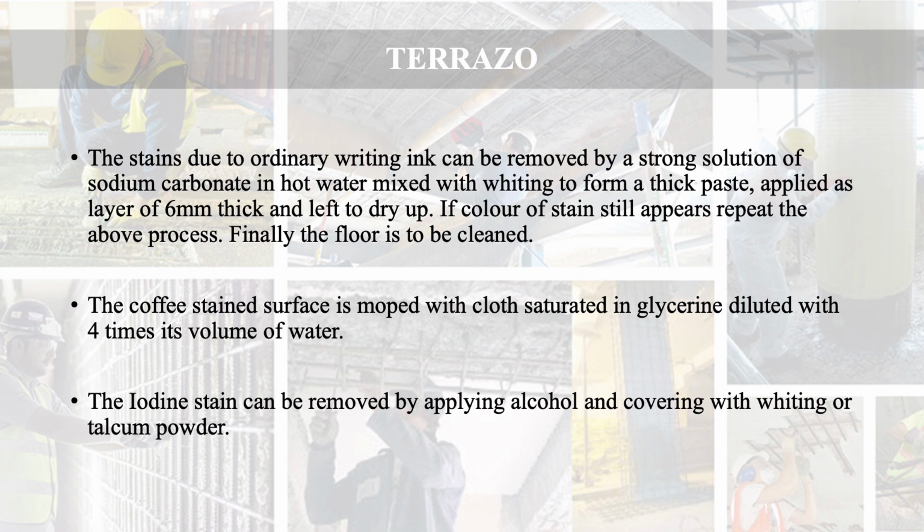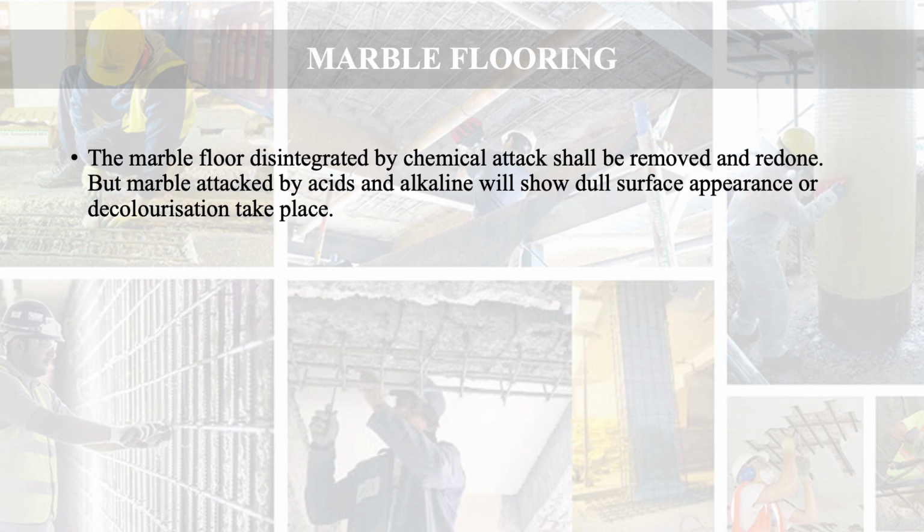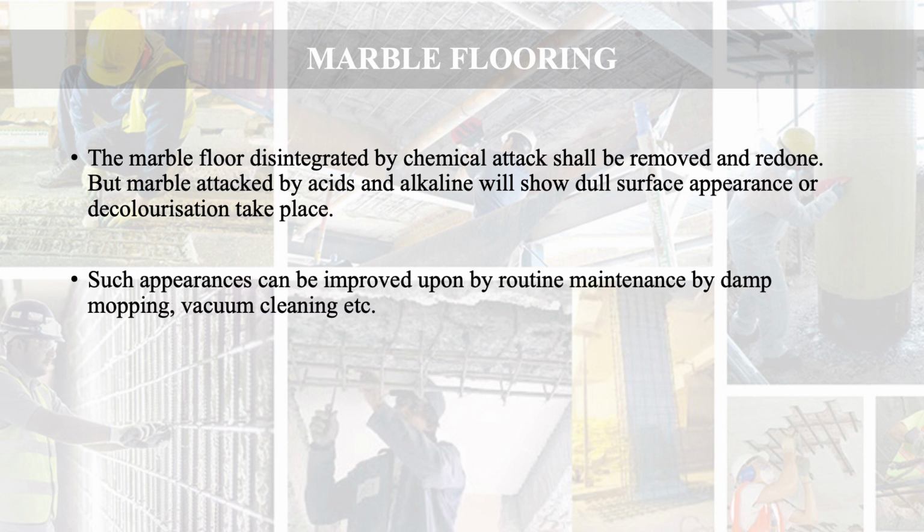Then we move to marble flooring. Marble floor disintegrated by chemical attack shall be removed and redone. But marble attacked by acids and alkaline will show dull surface appearance or decolorization takes place. Such appearance can be improved upon by routine maintenance by damp mopping and vacuum cleaning, etc.